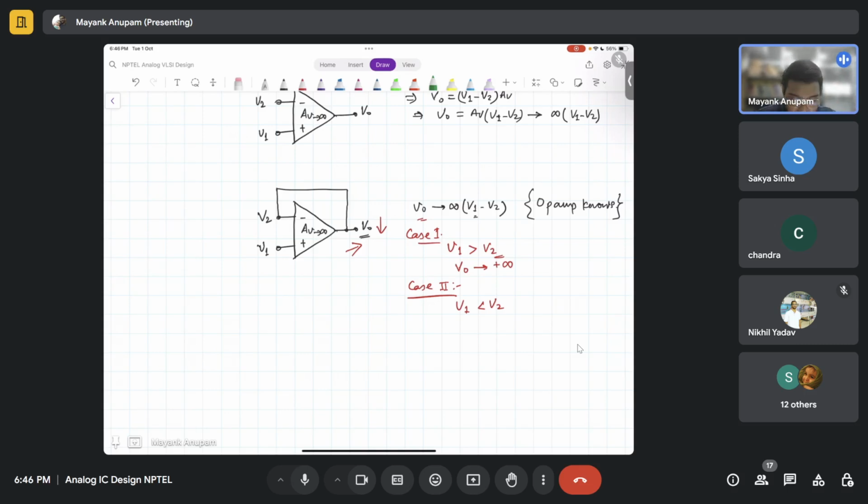The moment V1 is applied here, everything happens in an instant, and this node will be forced to be equal to V1. So it is purely an abstract concept just for our convenience. What I was thinking was that because the op amp input impedance is infinity, no current flows between V2 and V1, so V2 must be equal to V1, but I think that conception is wrong actually.